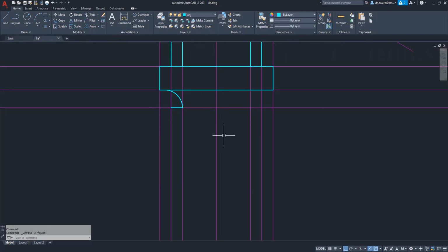So, interesting, they may also have, because they didn't give us a detailed view of it, they may also have had the assumption that this arc was going to continue out around to here rather than it be a chamfer, because that would be another acceptable way to terminate the threads going into this bolt if they had a tool that was just totally rounded all the way on the ends. Interesting. I think I might do that instead. I bet you that's what they had in mind.